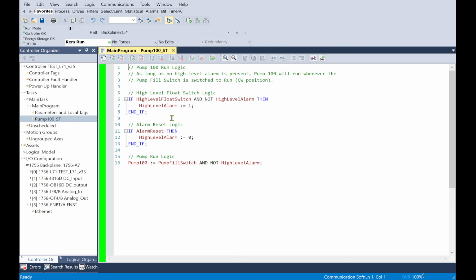Likewise, if you're trying to do some Modbus mapping, you're trying to arrange data, you've got to swap bytes and a bunch of weird, hard stuff. You're trying to package data for messaging, packing and unpacking data. You're trying to do some calculations or even some analytical type stuff or some statistics, high level math, and it's kind of in the back. It's not really controlling the logic. Structured text is the way to go,